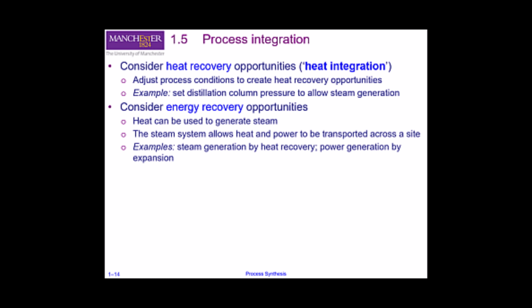Next, we consider energy recovery opportunities, that is the heat recovery and work recovery. For example, we can generate power when we expand pressurized fluids, or we can generate steam via heat recovery and then use that steam to do work instead of importing power, for example, in steam turbines.